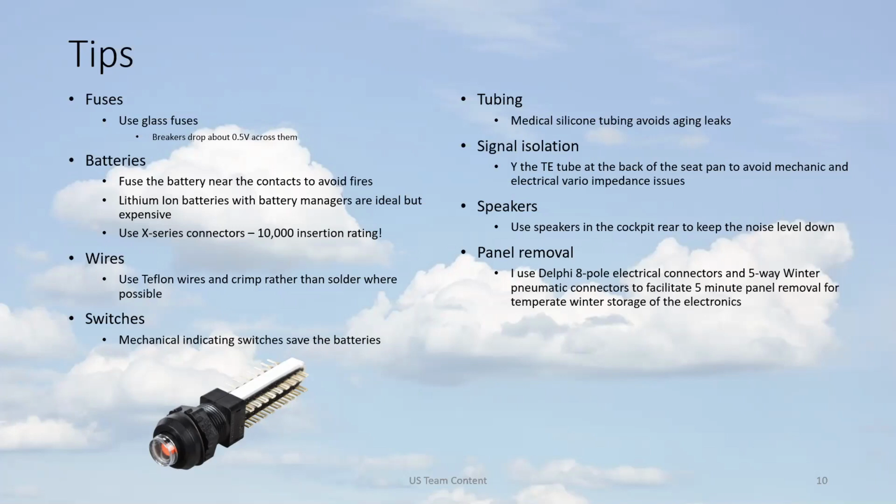And ideally, you take 2 separate feeds from the total energy tube at the tail, but that's a drama to do. But separating them at the back of the cockpit is a good compromise. I've done that on my last couple of gliders.